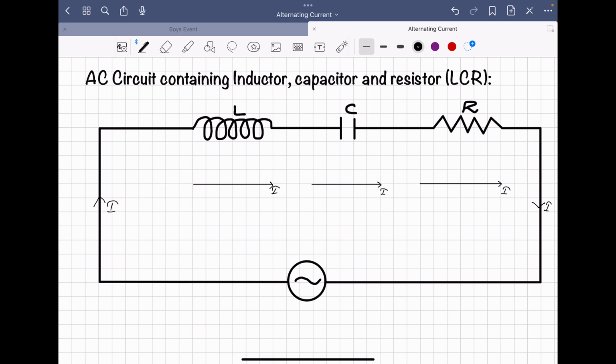First come to the resistor. As you know, in a resistor there is no phase lag between the potential and current. So the potential drop across the resistor is along the same direction as the current. We can draw the potential drop across the resistor as this, VR. There is no phase lag between I and VR, as both are from left to right, the same direction. Yes or no?